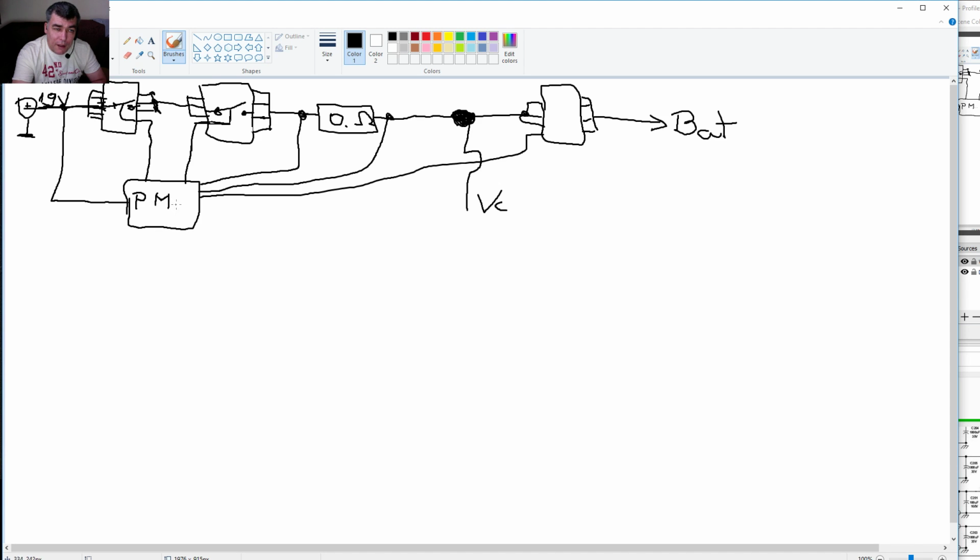On the other hand, obviously if you have a short on the motherboard, anywhere, because here you'll have all the power supplies, doesn't matter what, you have a short. This current resistor will tell this chip it's a short, and this chip will cut the power down. If you have a short here, the voltage on this resistor will be high, and the chip will read this.